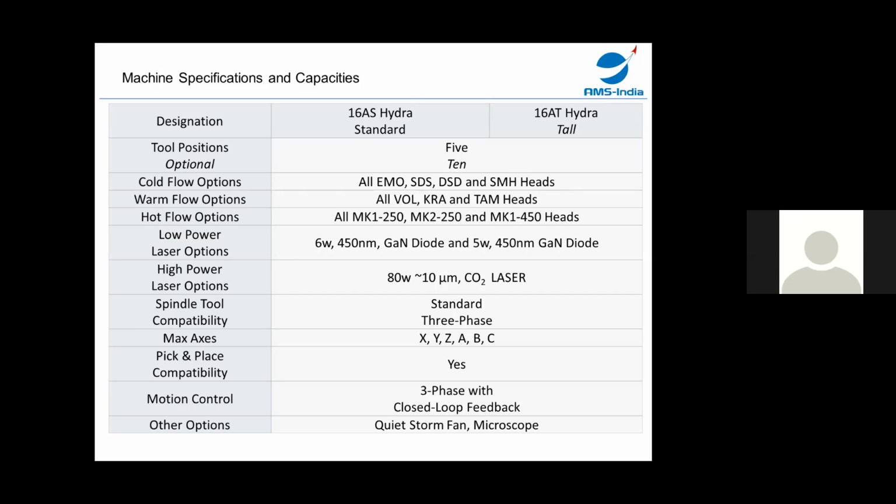And then it also has a pick and place capability. It has a gripper which can be programmed for segregation. You have hundreds of bolts and nuts coming. You can make the machine pick up each bolt and put it under a laser head or under an inspection fixture. It is okay to put it in a bin, otherwise throw it out. So you can also use it for segregation of waste. This is very useful. You can have a conveyor-like attachment where the parts keep coming, and this gripper can be used for segregating the parts, depending on the type or the color or the shape or the size, or any feature that can be measured.